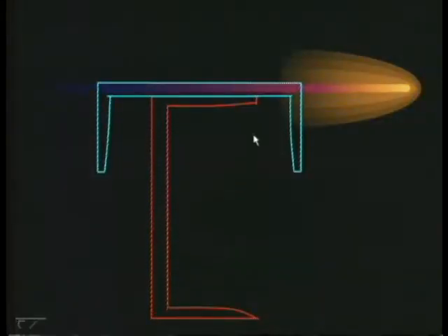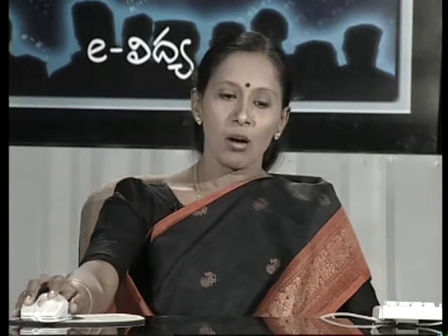Look at this. This is a channel, this is another channel, right? So these are the various possible types of sections that we can choose in case we opt for a built up beam. And now what if a built up beam is also not sufficient? The shear forces are very large, then you need a section of much more depth. Then what should we do? Yes, the topic that is going to be followed will tell you about all that.